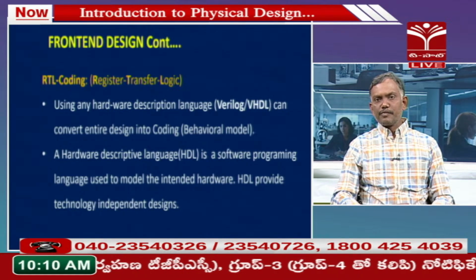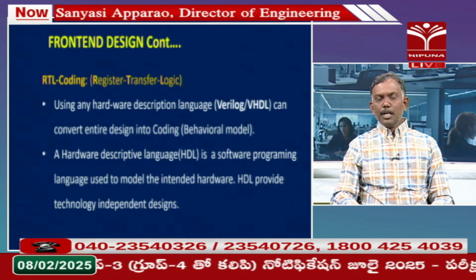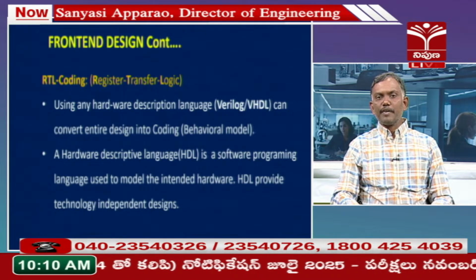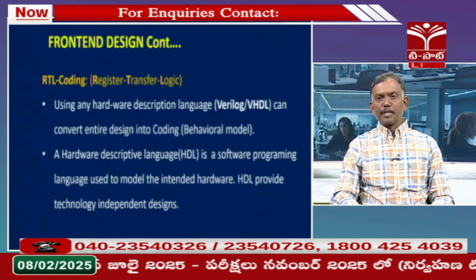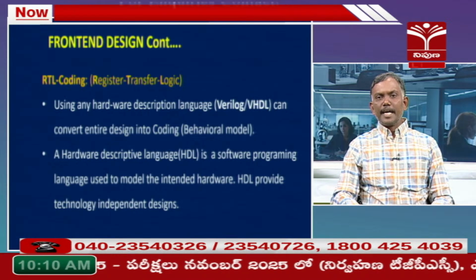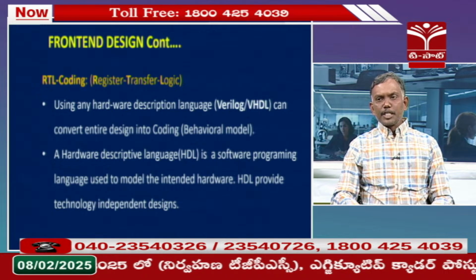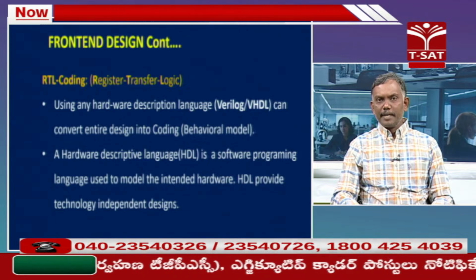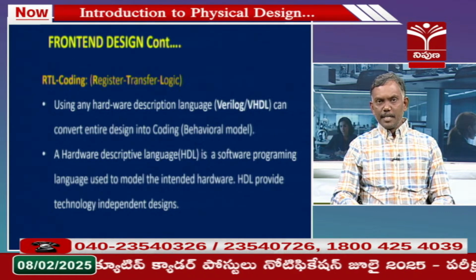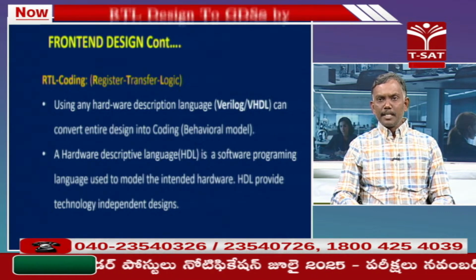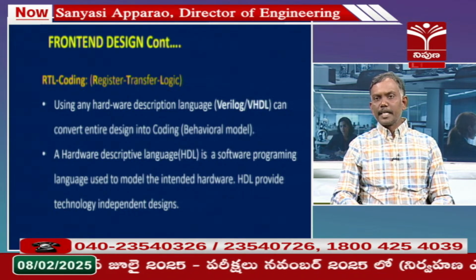RTL design team, first one is the RTL coding. RTL means register transfer logic. Using any hardware description language like Verilog and VHDL, these are the two hardware description languages, you should convert the entire design into code. And a hardware description language is a software programming used to model intended hardware. It is technology independent, means this RTL we can target to any technology node. Of course, we can see more details on the technology related.